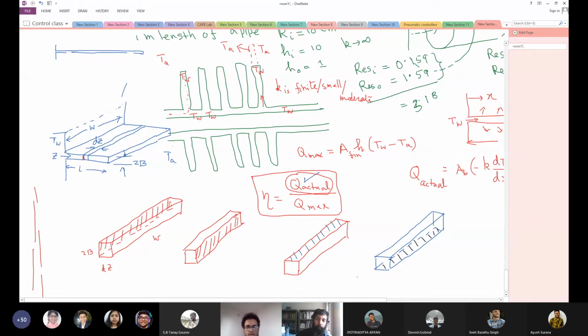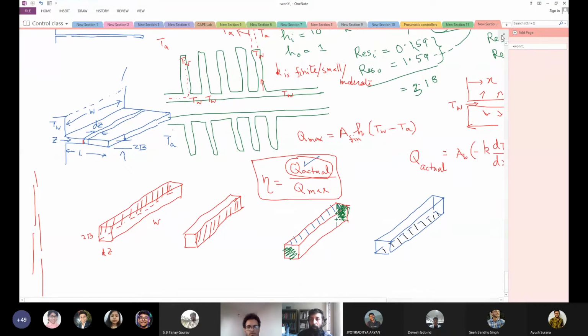What about this plane? Convection. What about this plane? Convection. What about this plane? Convection. Okay. So these planes, as we said, this 2b is very thin. So 2b is almost a differential. dz also differential. So the product of two differentials is very small compared to the others. So you neglect heat transfer through these green shaded planes. Heat transfer through other planes: write a heat balance for this differential volume, and be ready to show it on the screen.